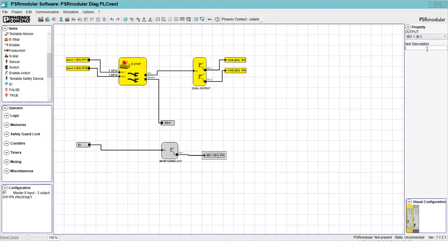Let's call it just a light. Okay, so this is a light. I have a separate monitoring output that comes on my B1, right? Again, it's connection number 8. And that is going to be, of course, enunciated by an external variable here. So we'll make that bit 0 from the input side. So now I've enunciated a couple of variables. I have some things going on in here. It's no longer just a simple e-stop. I'm also doing some enhanced diagnostics with it. So I will check and validate.